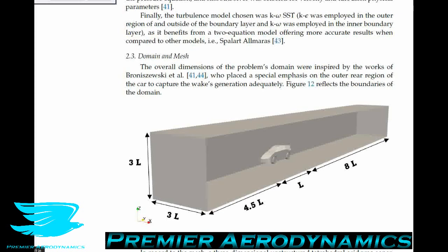So one thing that is a little bit alarming though is the mesh was a little interesting because the average Y plus was 40. This is very high. For a steady state simulation, you won't have as many problems getting it to converge with this Y plus, but still it won't help with the accuracy. And just as a side note, if you were to ever switch to a transient CFD solver, then that Y plus should definitely be dropped. Otherwise, there is a good chance that the simulation will diverge. So using steady state is a good way of effectively being able to cut corners and not have to drop your Y plus as much. So I mentioned cutting corners in a facetious way.